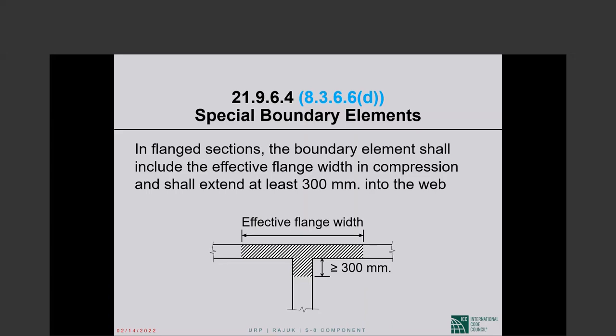Again, something that has been discussed before. If we place a shear wall in the first two floors of a five-storied building and this continues to other top floors, does it lead to irregularity? You have to figure that out by the criteria we discussed, the tables of vertical irregularities. So check them, and if you do fall under them, yes. If no, then no.